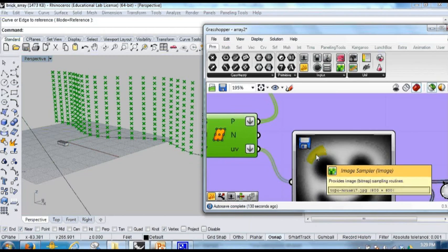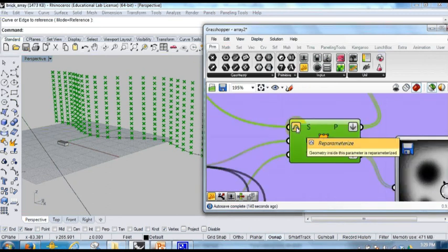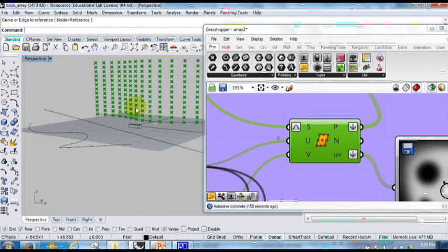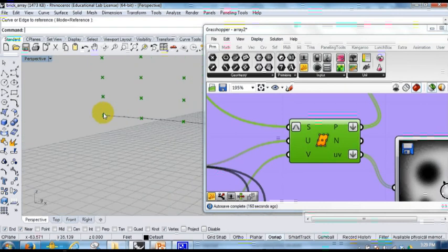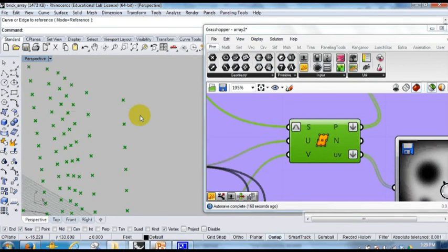Question: when you reparameterize the surface, what does that mean? Because it's kind of 0 to 1, where 0 is the center and then 1 is the outline of the surface? So how does that work? Yep, a good question. Reparameterize a surface means I put 0, 0 in one corner. By default, this will be different. And 1, 1 after reparameterize should be this corner.